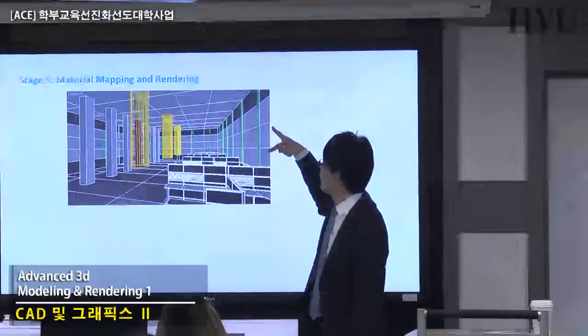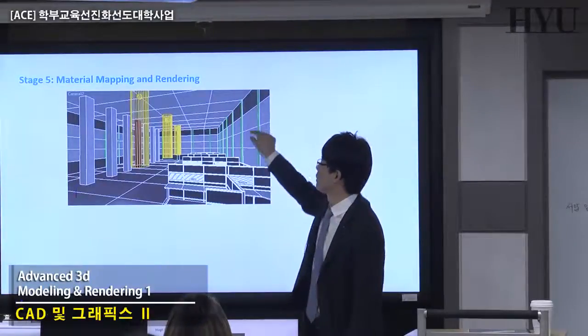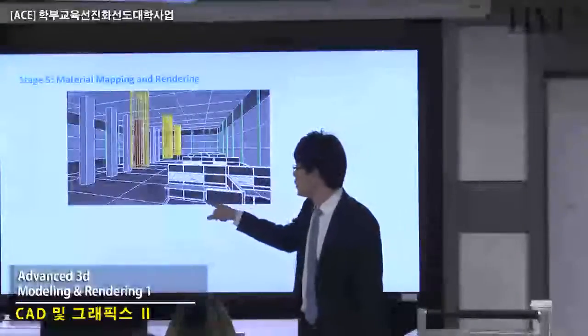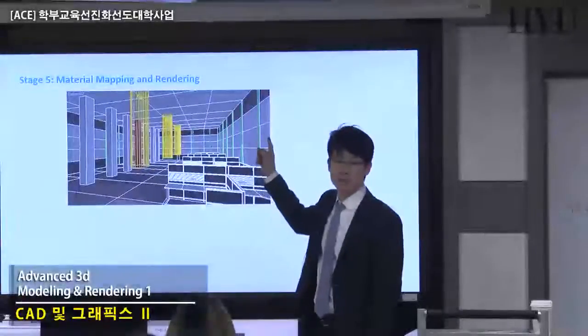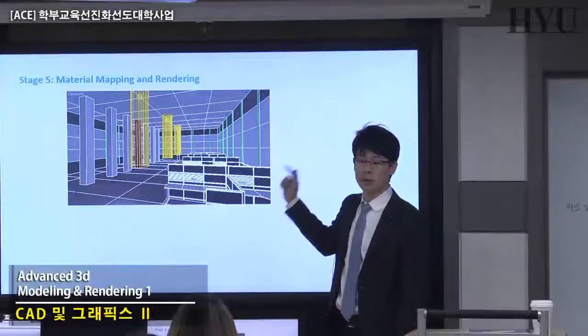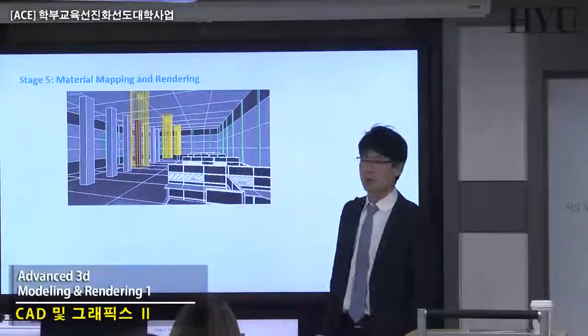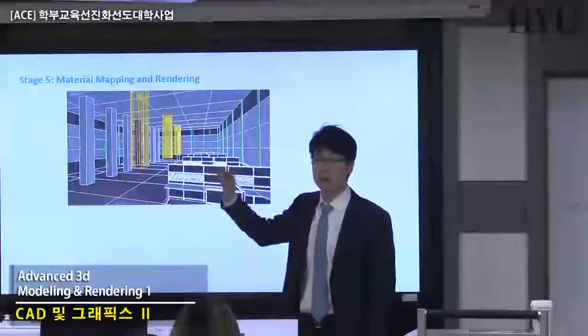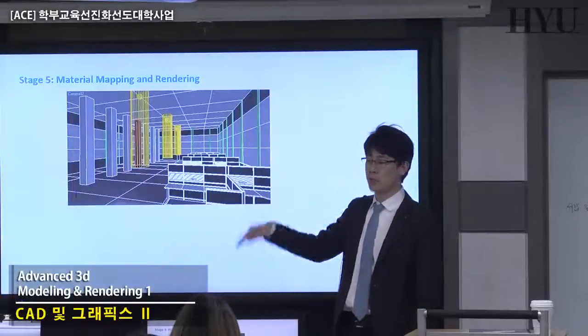And you can assign a texture map one polygon by one polygon if this is an editable poly, not just a box, okay? That's why you have to convert it. I'm going to tell you how to select some of the polygons, and how to assign different material.